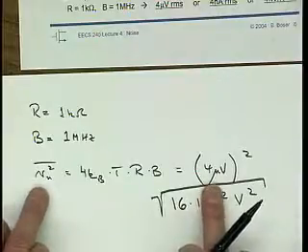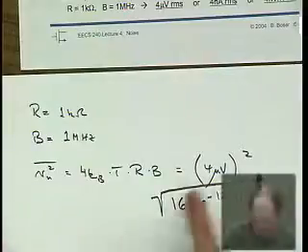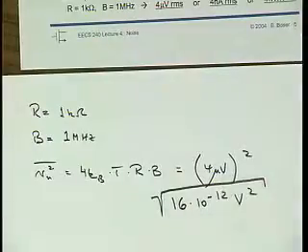One meaning of this is, if we had a sinusoid and we were adjusting the amplitude of that sinusoid so that it produces exactly the same noise power as this 1 k ohm resistor, we would have to adjust the RMS amplitude of our sinusoid to just these 4 microvolts. Okay, so now we have it.